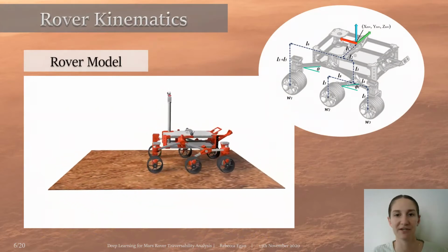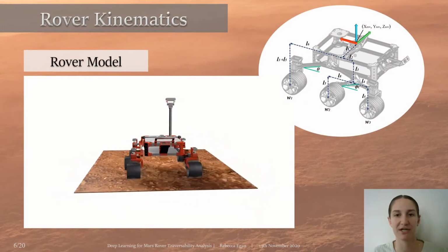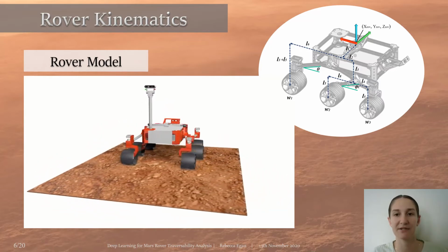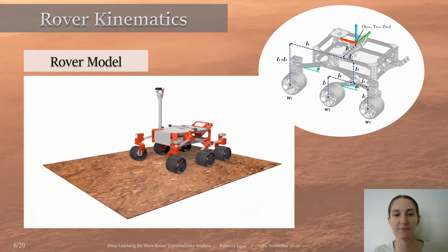The SORPY rover is utilized to model the layout, proportion, and rocker bogie suspension of the Curiosity and Perseverance rovers. Based on the Mars Exploration rover parameters, an obstacle height limit of 12 cm, yielding a maximum pitch of 25 degrees, is defined.